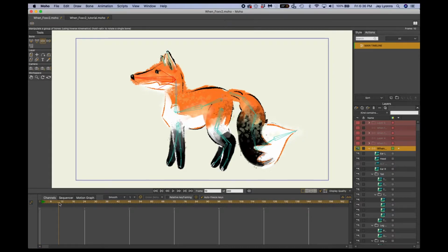If you've accidentally bumped this playhead, you might notice that a bunch of tools are missing in the left-hand side panel. If that's the case, just check your timeline and make sure that you're in frame 0 to begin editing and designing your character. We'll move to frame 1 and all of the other frames within the timeline only when we're animating our character's positions.